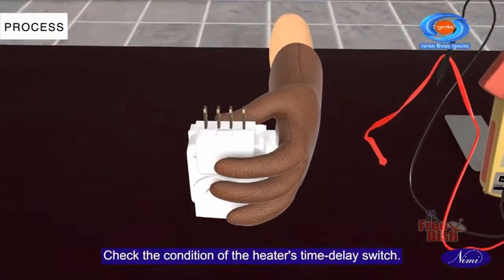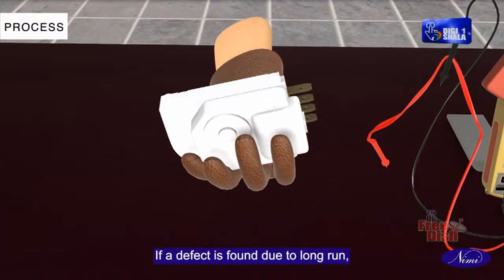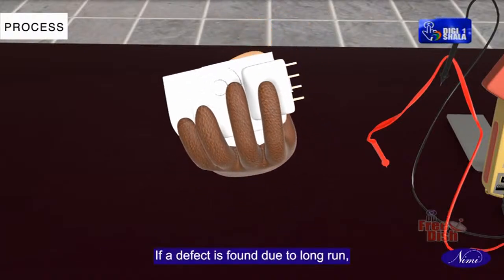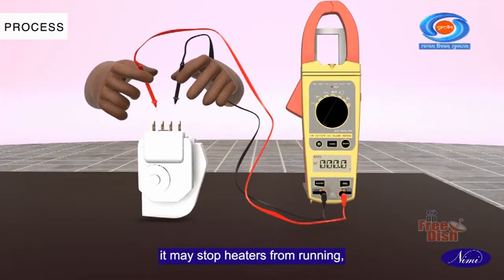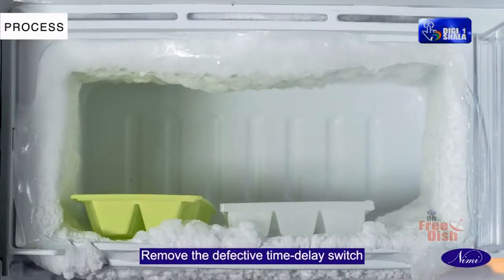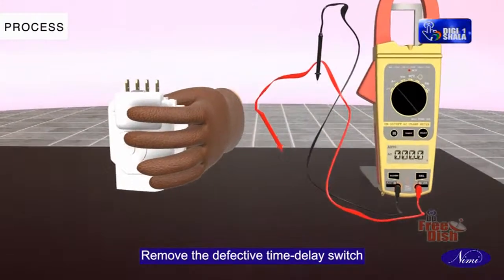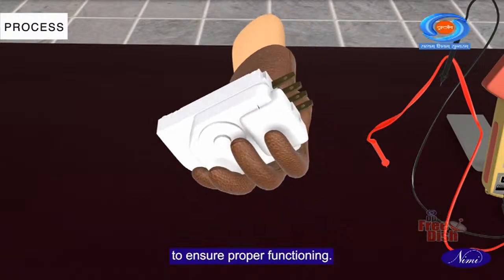Check the condition of the heater's time delay switch. If a defect is found due to long run, it may stop heaters from running, leading to frost accumulation. Remove the defective time delay switch and replace it with a new one to ensure proper functioning.